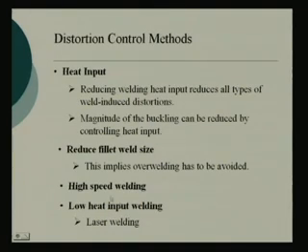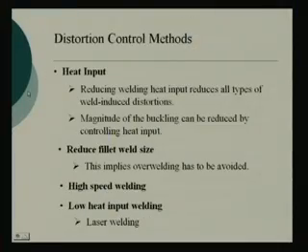That same thing can be talked about, given a name, as low heat input welding. As you can see, the first we have mentioned is laser welding, but laser is not a low heat input welding. That does not mean a welding with a heat source whose heat generation capacity is less. No, it is actually low rate of heat input basically. So heat input, speed of welding, low heat input welding, these are one and the same thing, connected with each other.